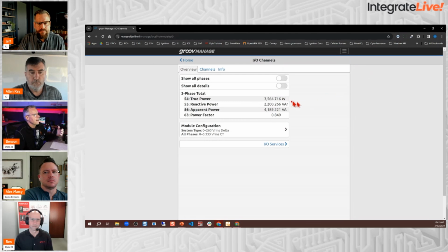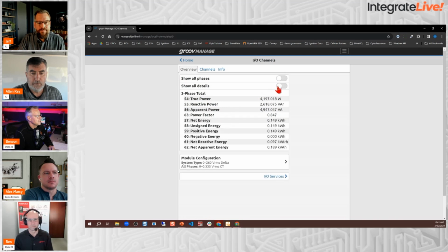And when I do so, now I'm getting the actual load information. So I can see I'm using about 3.9 kW, or 3,900 watts, up to 4,000 now. And I've got my power factor in there. And just in the few clicks there, I'm starting to get some really interesting information. I'm also getting how much energy has been used since I booted this thing up. So you can see already my kWh, which is, of course, energy over time, is starting to accumulate. So that's all good. I'm really looking good here.